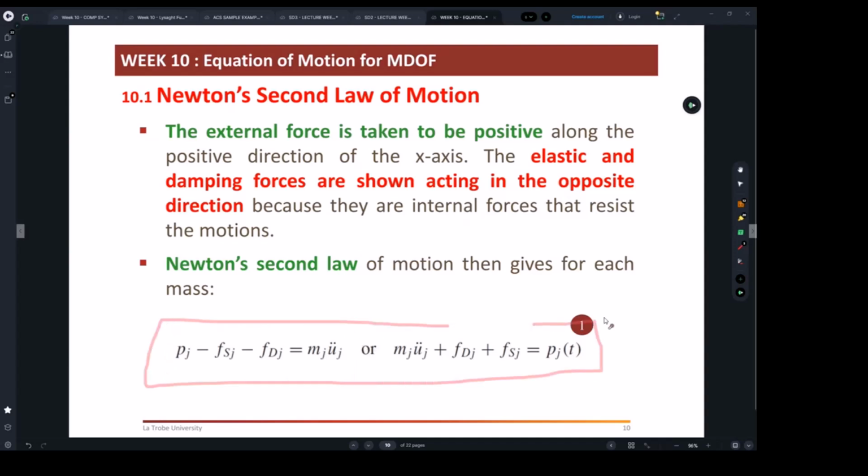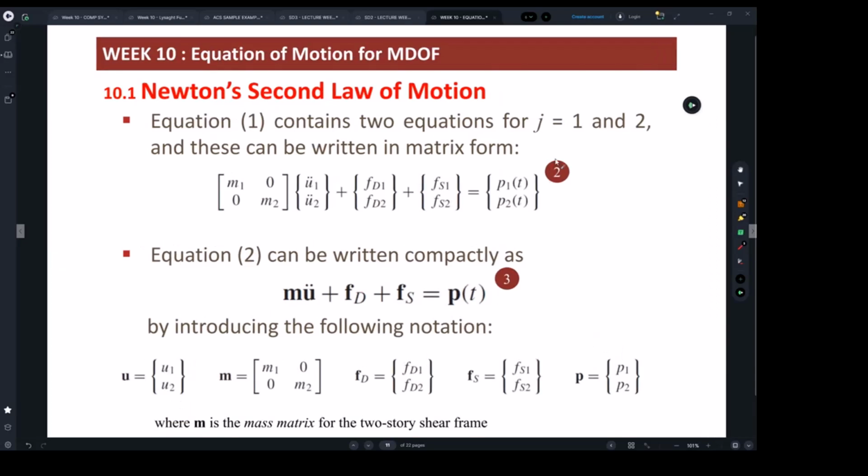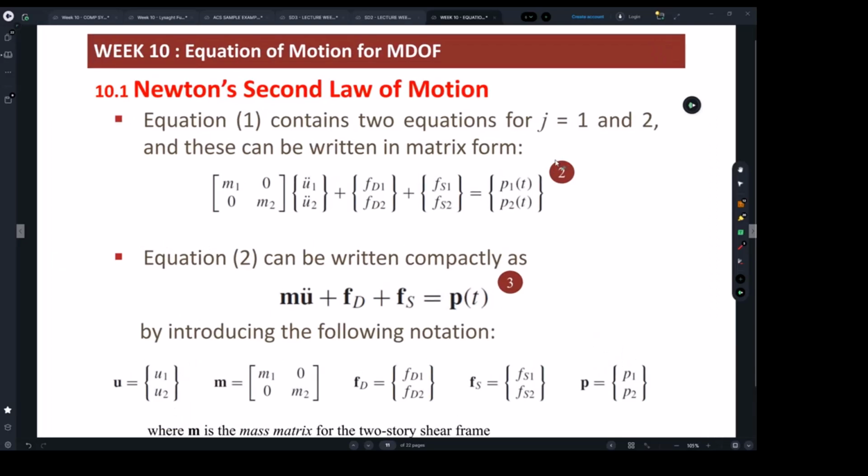But at this stage, equation number 1, it's still talking about j's, and in the next page, because we have 2 floors, mathematically, to represent that, we're going to employ the topic of matrix. So that's from where the matrix is coming, because we have a system with 2 independent motions, and level 1 is not dependent on level 2. Yes, they are in function of the columns and damping systems, which are shared.